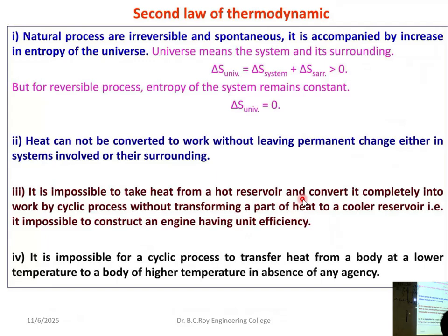So then cv ln P2 by P1 plus cv ln V2 by V1 plus R ln V2 by V1. Then cv ln V2 by V1 plus R ln V2 by V1, you can write cp ln V2 by V1. Yes? Isn't it? Can do that.